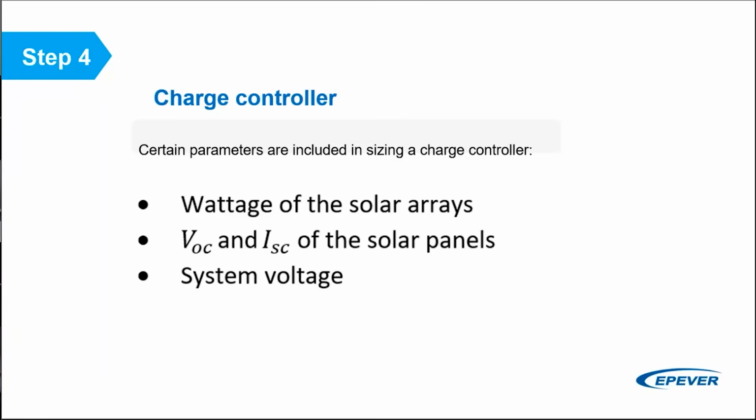But MPPT charge controllers use a charging control technology that ensures delivering maximum available power from the solar array to the charge controller. Unlike PWM controllers, non-matching voltages from panels and the batteries are not a concern, because the MPPT charge controller will convert the extra voltage from your PV panels to current, so that you have less loss in your system.